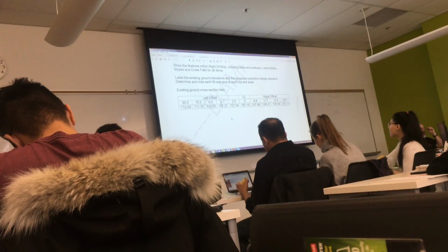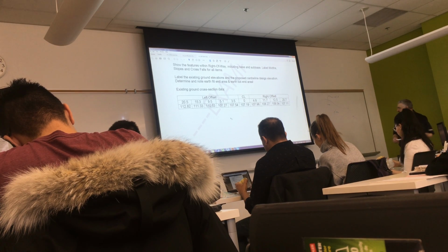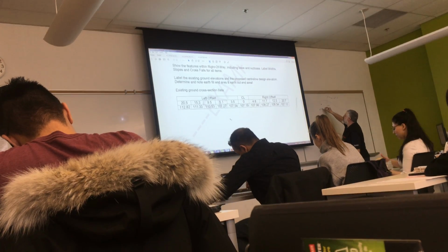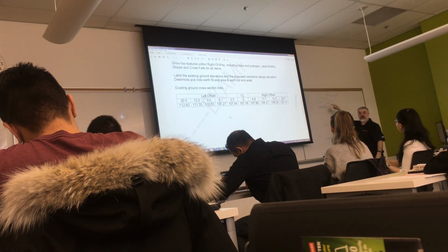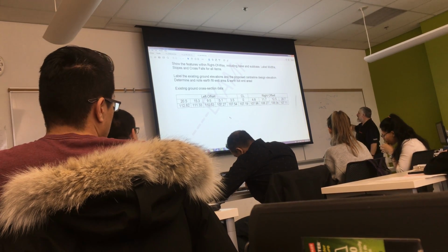The existing ground shows, if you remember the cross section, I'll go back to this from last week. The plan view shows points described by the station and the offset. Remember this? That's what we're plotting, station offset, station offset. That's how we describe the points in this plane. In this plane, we describe everything by station elevation.